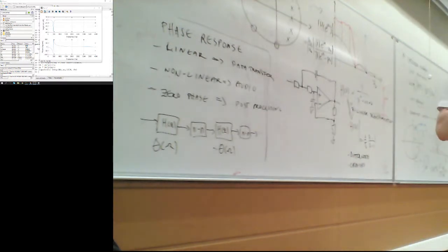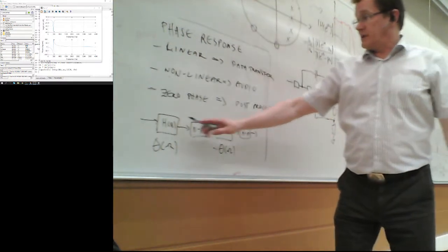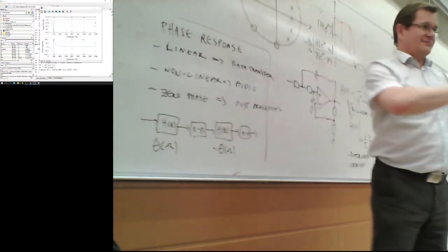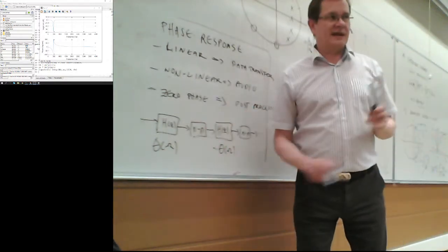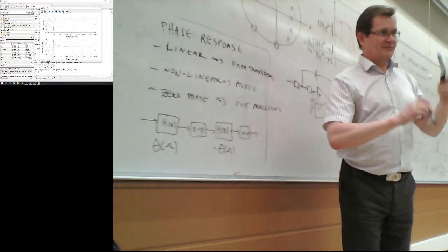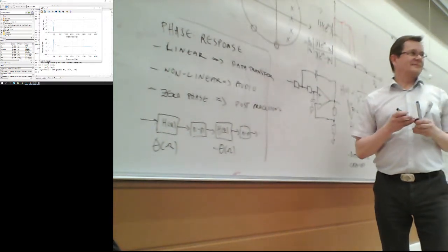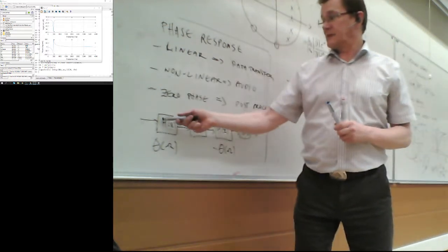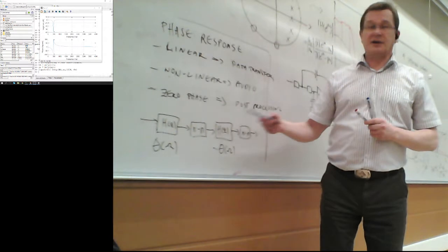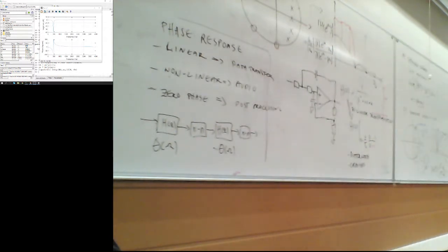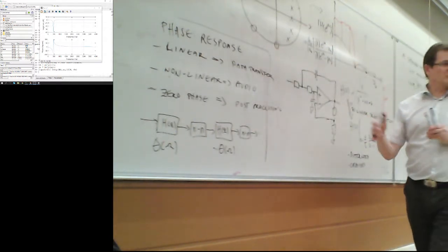Yeah, the amplitude response would be twice the effect. So if you have 80 dB attenuation, that will become 160 dB. But on the other hand, if you are targeting, say, 80 dB, then you would have 40 dB and 40 dB stop band attenuation. Works only for post-processing.